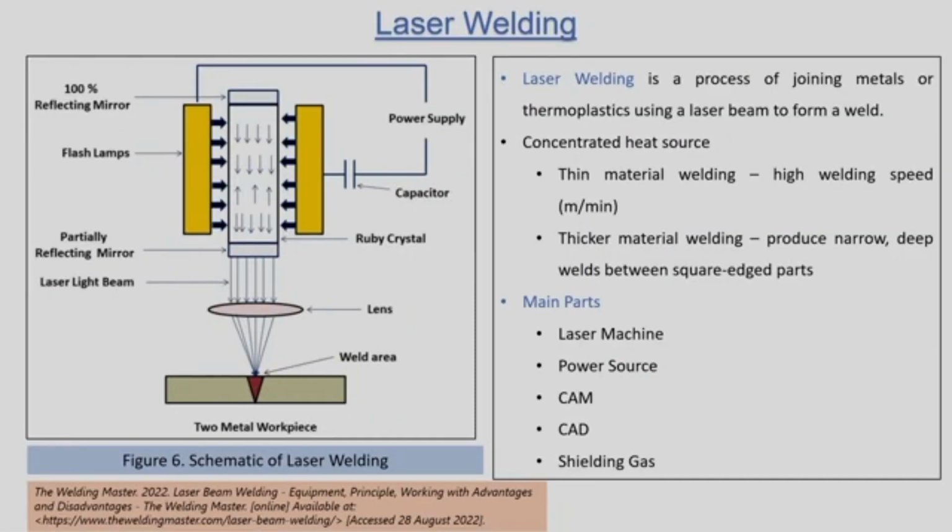So, the laser welding process is a very simple process. Here we are joining two different parts together by using the heat generated by lasers. We apply the lasers at the location of the interface of two parts, and the photon energy is converted into thermal energy at the laser material interaction site, and we are melting the work parts.